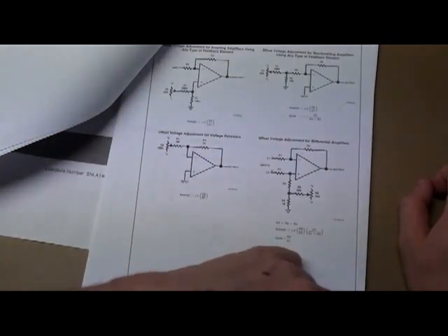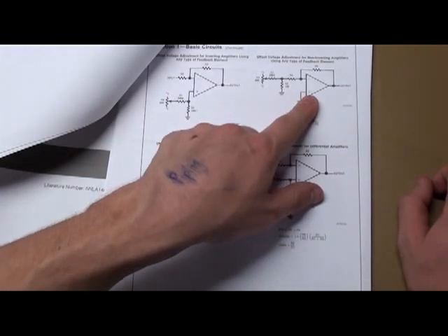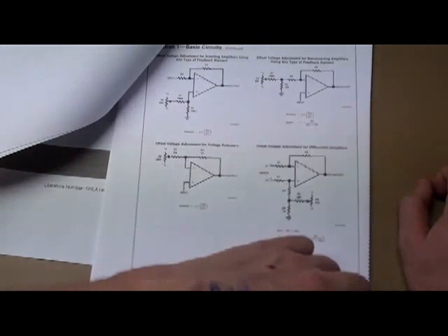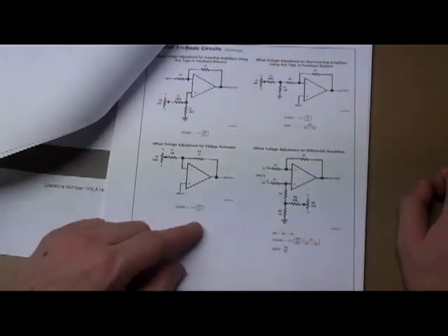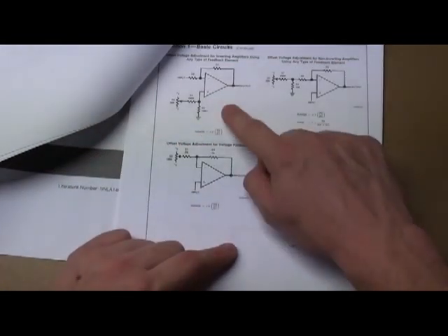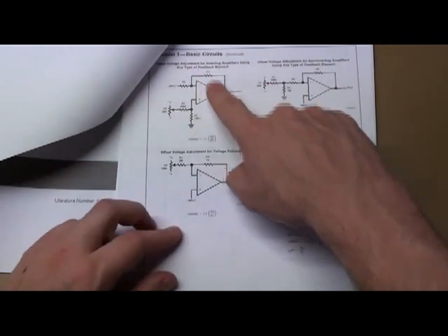Basically inside there, it's got a bunch of these triangle dudes, op amps, and a bunch of resistors that are configured to increase the common mode rejection ratio, which is what we talked about earlier. The other thing I want to point out are these offset voltage adjustment amplifiers.